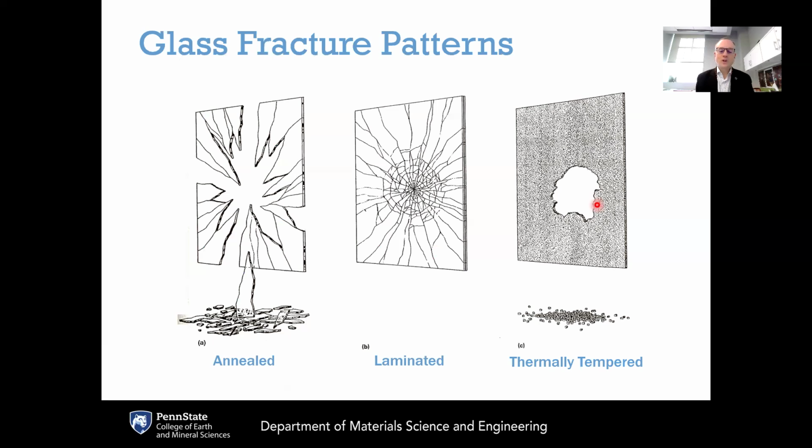When that happens, there's still a lot of tensile energy that needs to be released from this tensile layer. So there's a lot of tensile energy that needs to be released, and it needs to be released faster. But the crack can't propagate any faster because it's already achieved its terminal velocity governed by the speed of sound. So what is the way for the crack to release energy even faster? The way to do that is for the crack to branch. And so when the crack hits that terminal velocity, the only way for it to release energy faster is for that single crack to bifurcate into two new cracks.